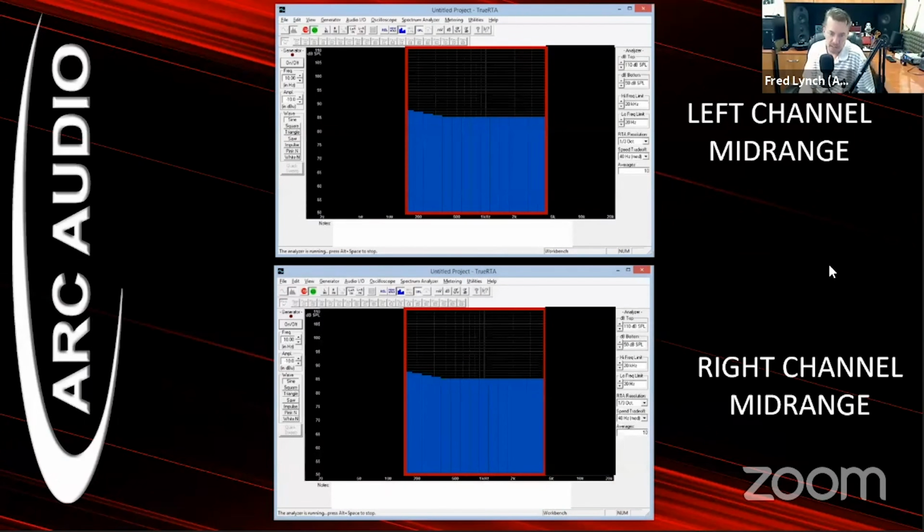Now, why are we doing this? We're doing this because you don't want certain frequencies to be louder out of one speaker than the other speaker. If you've ever sat down in a higher-end installation and listened to a real detailed jazz track, a problem which sometimes happens in systems is that at a moderate level, all of a sudden the vocalist starts getting louder, and she goes from the center of the car and starts pulling off to the left-hand side or the right-hand side of the car.